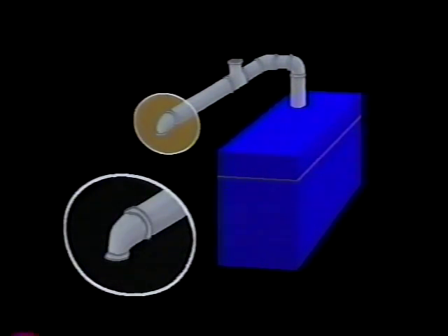At the far end of the header, notice there is a reducing elbow with the small end looking down. This is tied into this vertical pipe called the equalizer. The equalizer's purpose is to allow condensate from the header to immediately return to the boiler, providing for drier steam in the header and for equalizing the supply pressure in the return pipe to the boiler. So boiler water doesn't get pushed back through the return piping as the steam pressure increases.